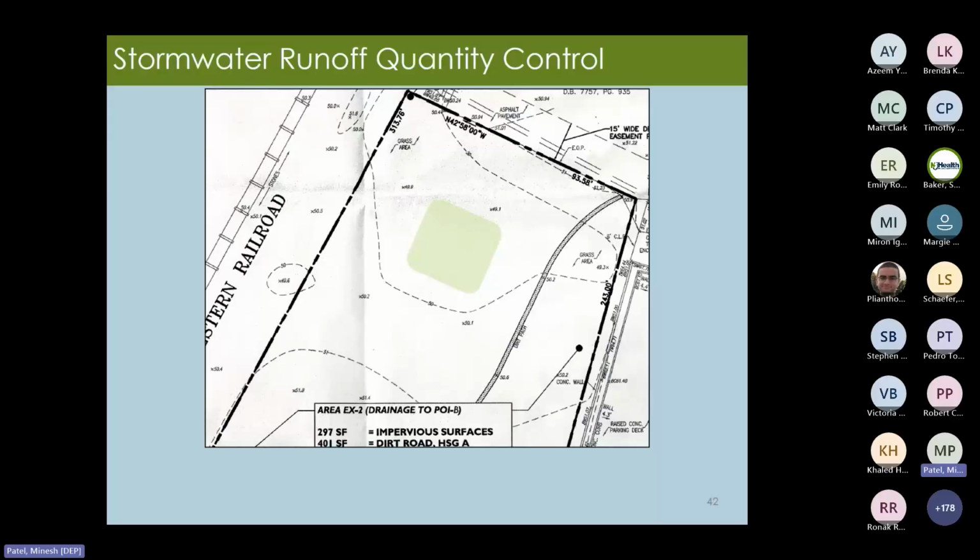So on that same example site that was shown a couple slides ago, there was a 6-inch deep ponded area within the shape that's depicted here. This was ignored, and the basin was made significantly larger than was needed. If there are any questions as to whether areas of ponding exist on site, and it cannot be determined from the photos of the site, you may just have to go there in person and see the actual site.